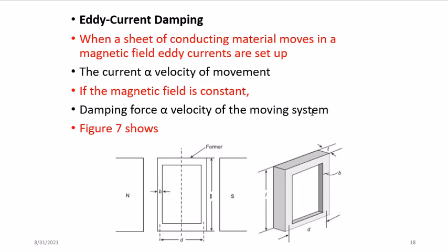So in this way, we create a current which acts in opposition. It will oppose the movement of the pointer when you connect it to any electrical source you want to measure. So it will create an opposite force, which is our controlling force.